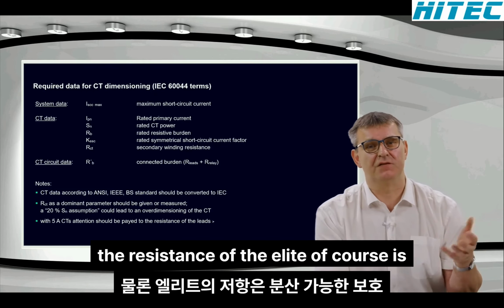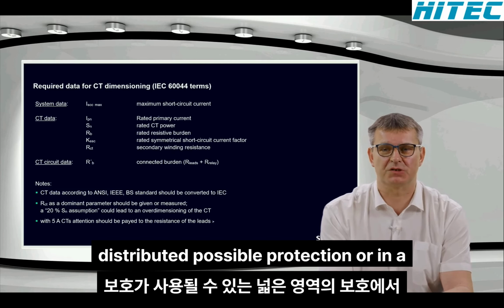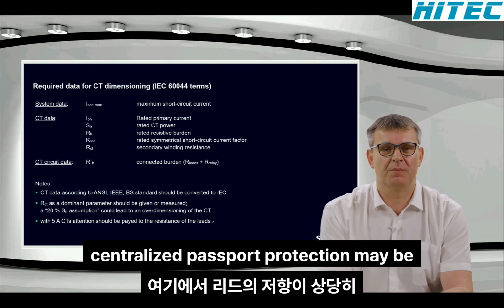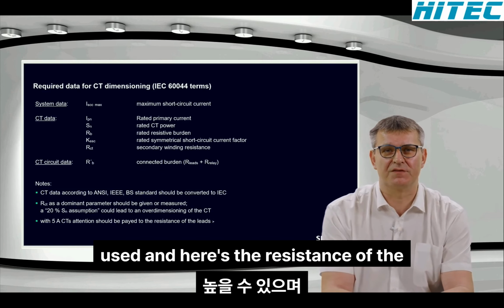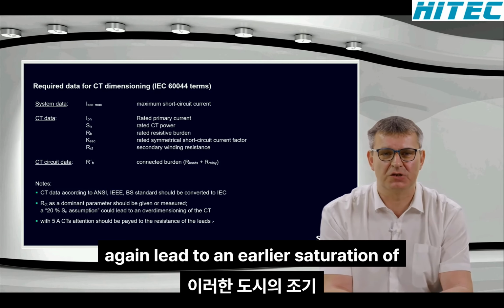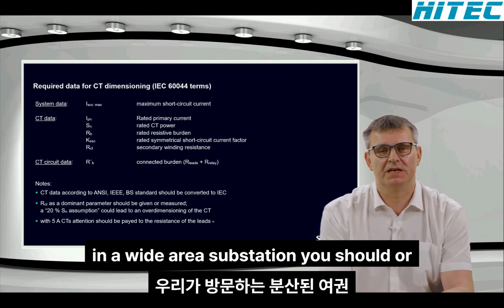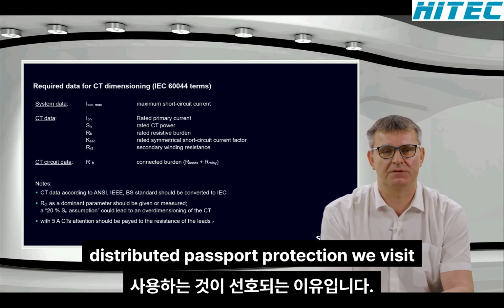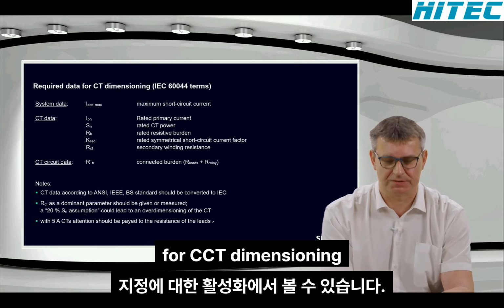The resistance of the lead, of course, is every time an issue in a distributed busbar protection or in a wide area busbar protection, when a centralized busbar protection may be used, and here the resistance of the lead may be quite high, which could once again lead to an earlier saturation of the CTs. And that's the reason why in a wide area substation it is preferred to use a distributed busbar protection. We will see it later in the equations for the CT dimensioning.